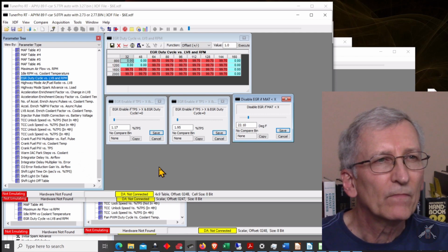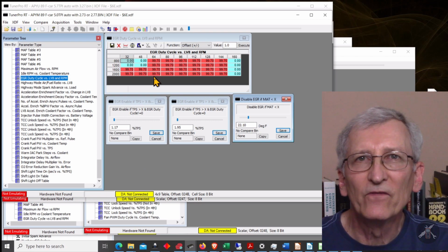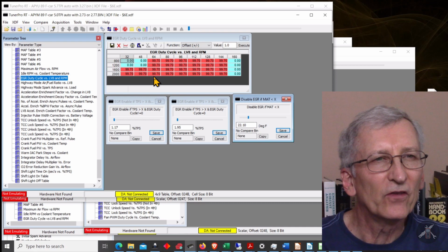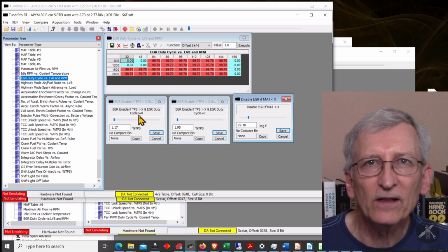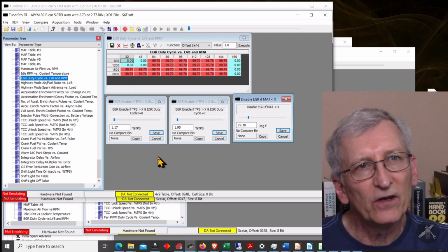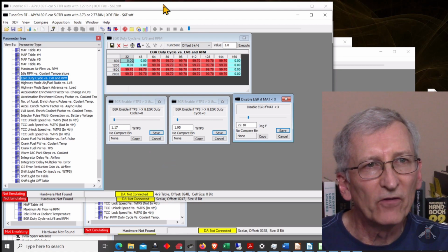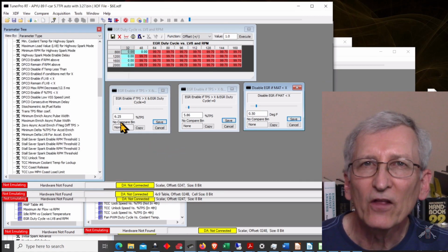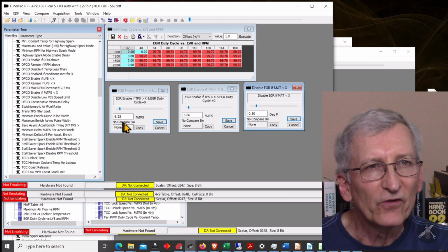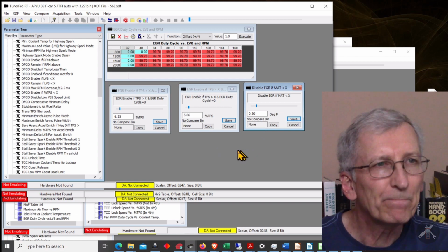And again, you've got the cycle or cycle exclamation point variable back in here. And it's right around 6% throttle that you're going to get this enabled. And again, if the inlet air temperature, manifold air temp, is above, and it's interesting how they switched values, because this one's back to degrees Fahrenheit and a half degree Fahrenheit, so again, down around 0.